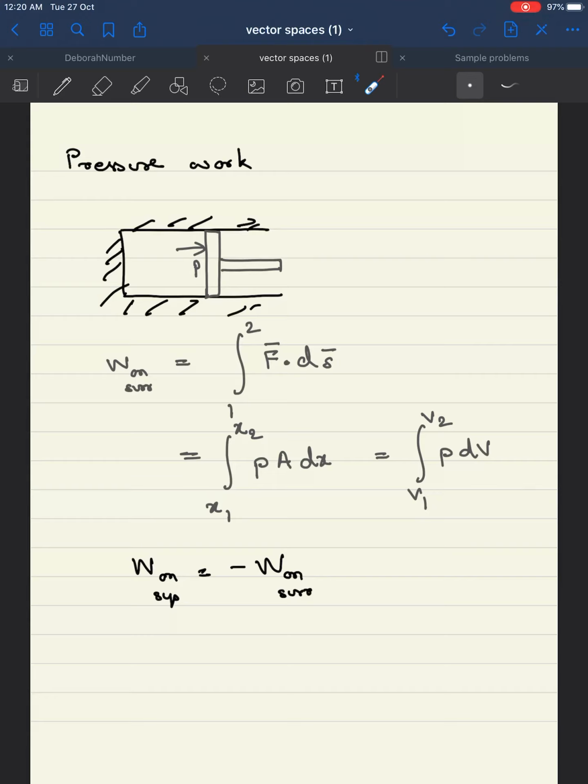Good. So I think what we have done is we have been able to look at all the different types of work, except one more thing. There is something called shaft work. I'll just tell you that this comes up quite a lot, and the reason it comes up in fluid mechanics a lot is because, for example, when we have fluid going through a pump, then you can have an external moving boundary impart energy or do work on the fluid and give it energy.